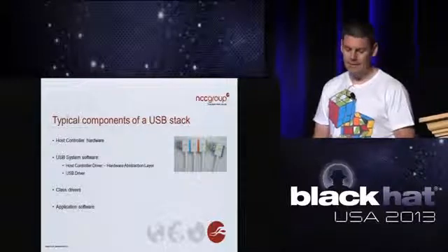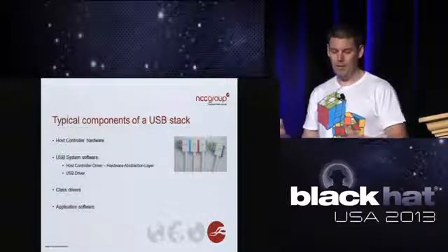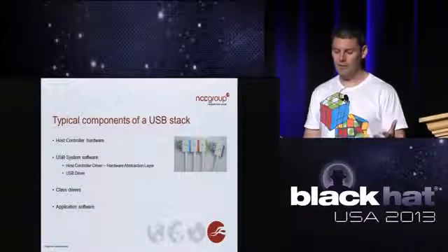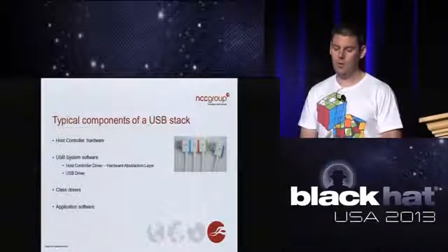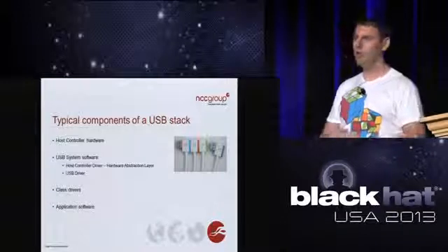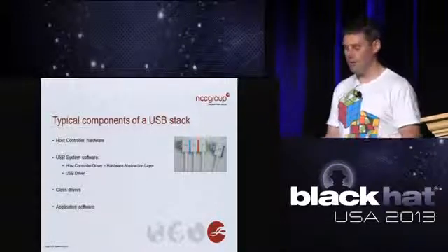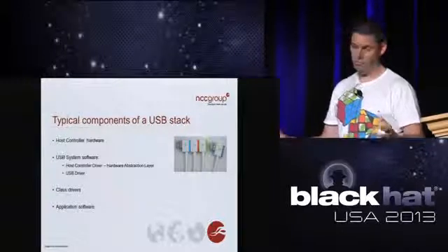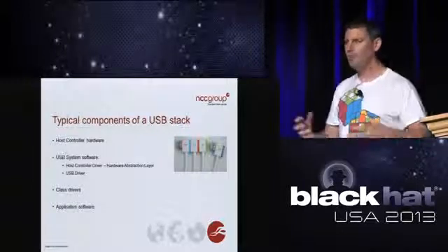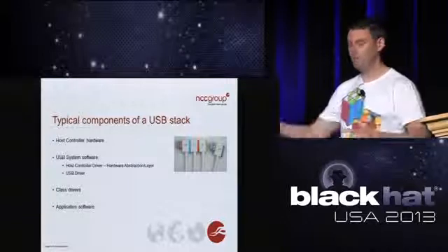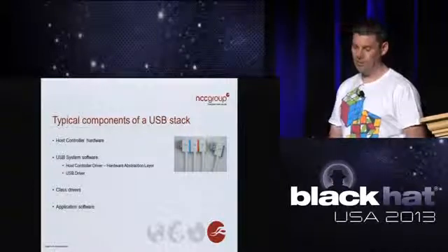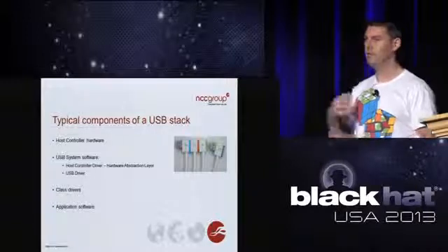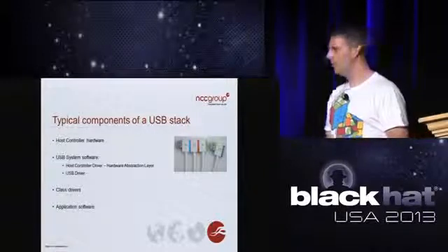Above the host controller, you'll have the host controller driver, which provides a hardware abstraction layer to the USB driver, which is the core component within the host that performs the enumeration that we just talked about and understands how to pass off information to the appropriate class drivers. Above that, you have the specific class drivers, so for example, a mass storage driver, printer driver, that kind of thing.